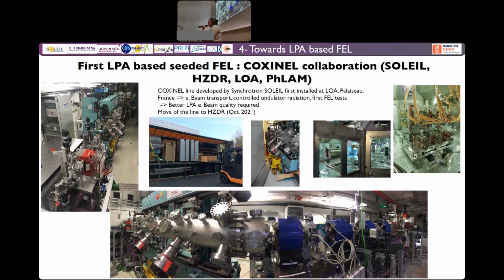to install and align. So you see here the permanent magnet quadrupoles, which are installed in the chamber of laser plasma acceleration. So we have special copper cables for good vacuum, for the connections on the vacuum. You see here the in-vacuum undulator. So the magnets are inside the vacuum so that we can close the gap to 4 millimeters to have a larger field. So this is typical undulators that we have at SOLEIL.